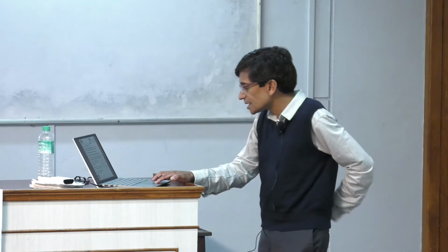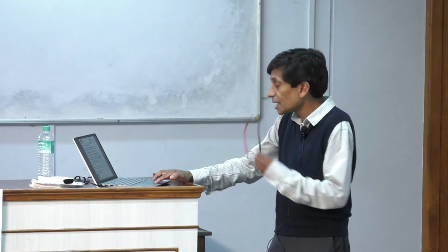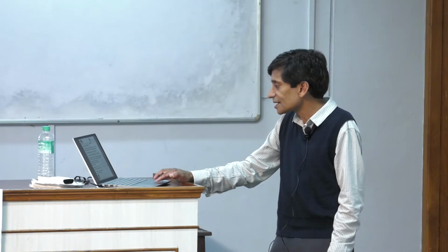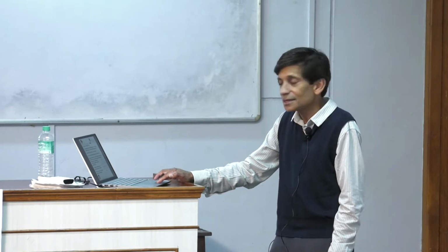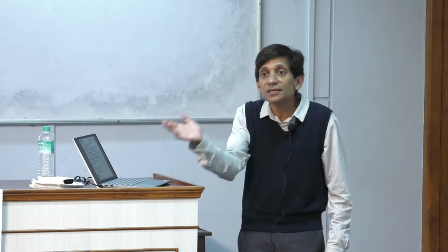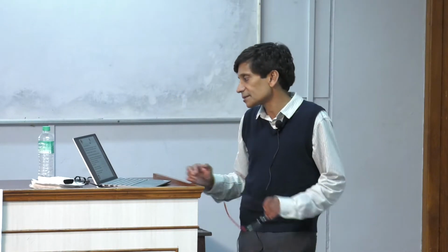So this is what I was explaining here. The feed flow comes here. We have a valve on the retentate side. And on the other side, the cake resistance and the membrane resistance, right? And the resistance must be the same for both flow paths. And that will determine how much flow goes one way or the other, okay?